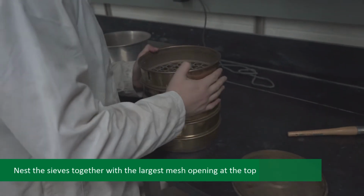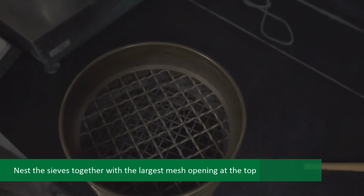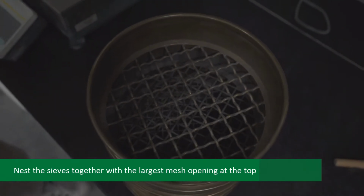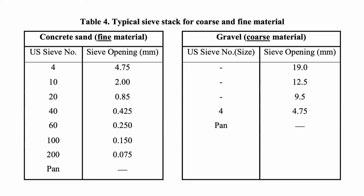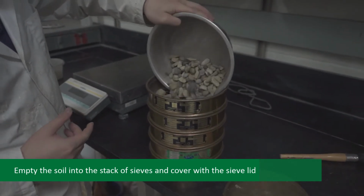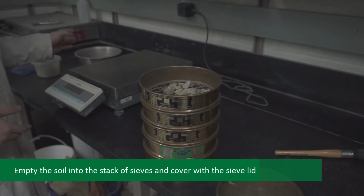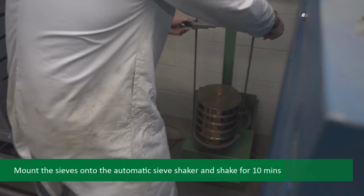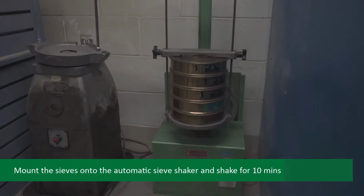Now, nest the sieves together with the largest mesh opening at the top and successive smaller mesh openings on the bottom. A receiving pan is also placed beneath the sieve with the smallest mesh opening. A typical sieve stack is suggested in Table 4 in your manual. Empty the soil into the stack of sieves from the top and cover with the sieve lid. Mount the stack of sieves onto the automatic sieve shaker and shake for 10 minutes.